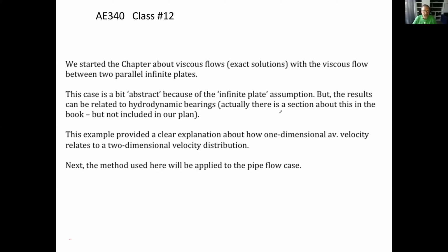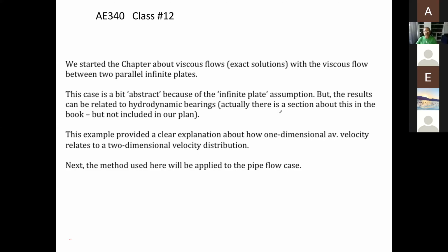I mentioned that the flow between two parallel plates is a bit a hard sell, because what is infinite? I mean, where you see an infinite. So the application of this thing is really to understand the hydrodynamic bearings, where you have a very tiny film of liquid to reduce the friction between two metal or two solid surfaces. And of course, in everybody's car, we have hydrodynamic bearing.